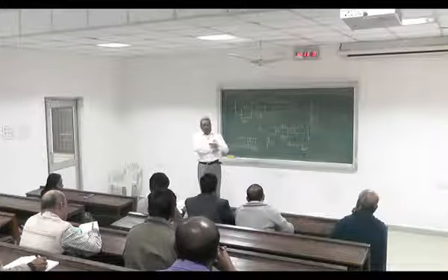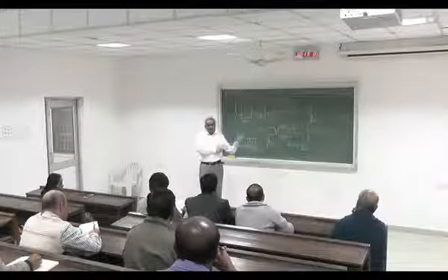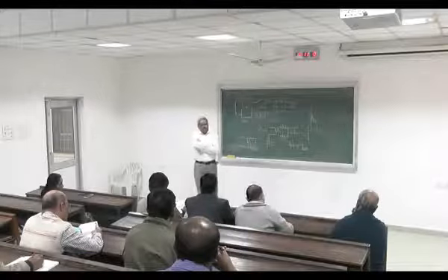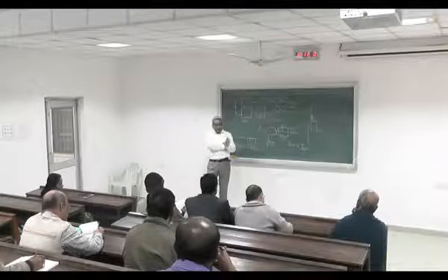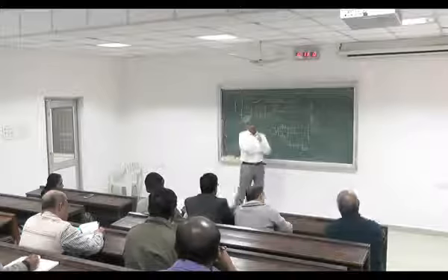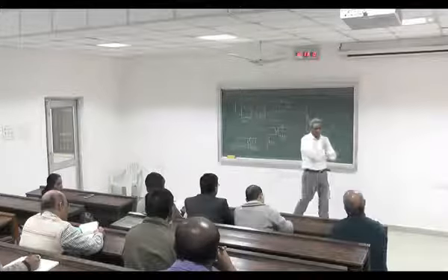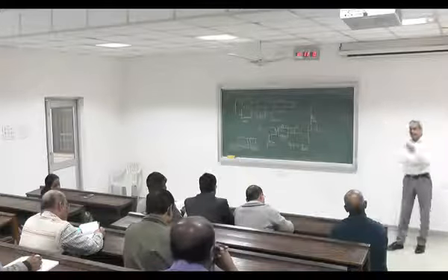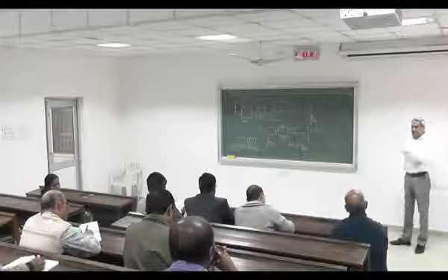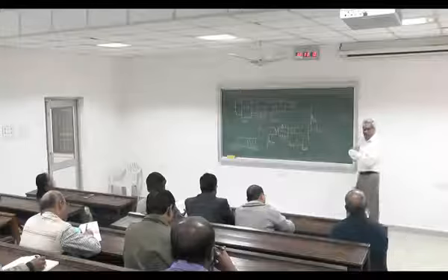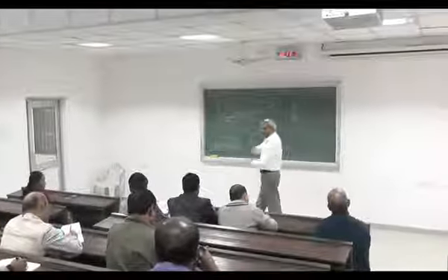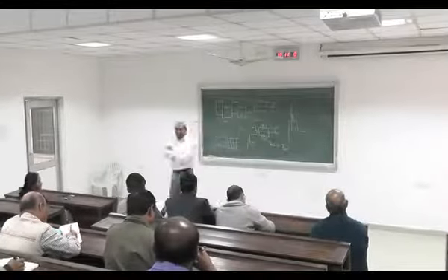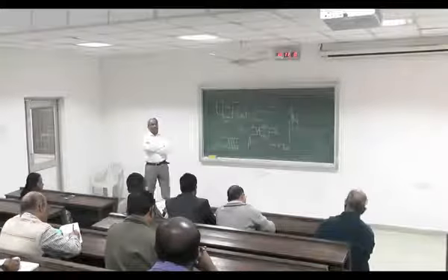So that is a big difference between the resonant and soft switching circuit. In the resonant circuit, your practical switching frequency could be much higher, because in the soft switching converters we have a lot of parasitic components which are not taken care of.